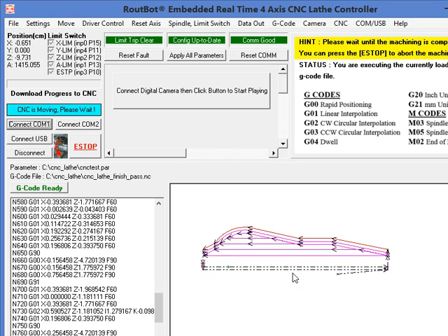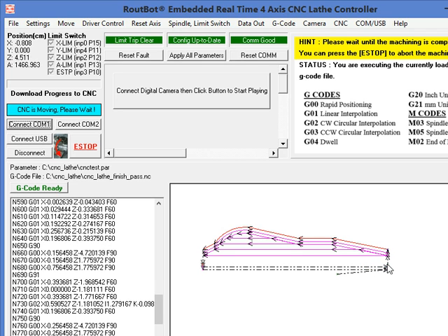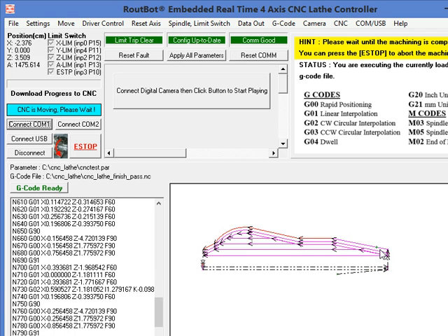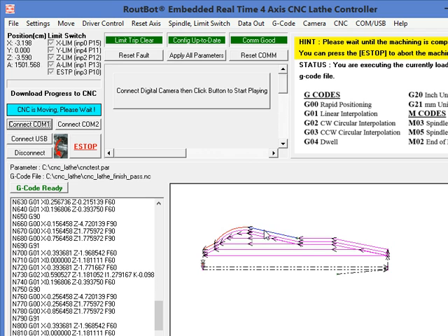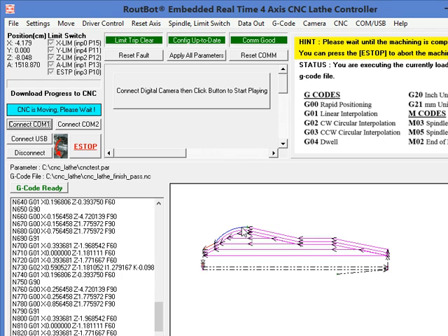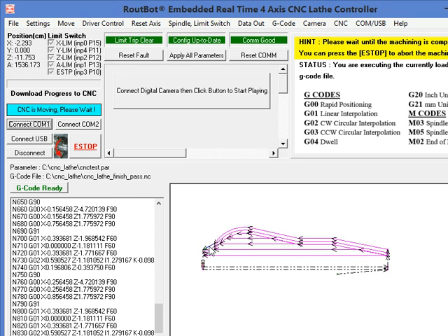So it did all the roughing passes. It did one finish pass at 0.1 inch inside the material, following the original profile strictly. And now it will perform the very last finish pass to give us the final surface of revolution that we wanted. And in this way, we get the most optimized result, the best finished product.